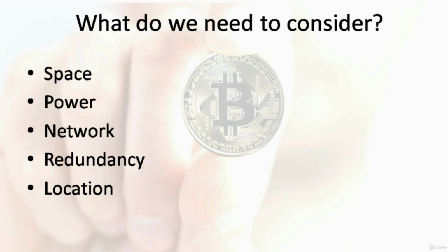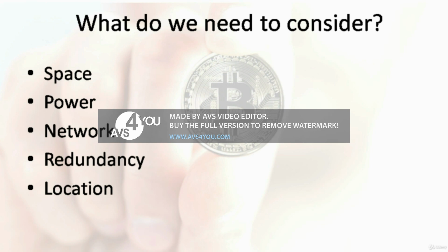The thing is that if you size it as stringently as possible, you might have cases where you have overload, or if you want to change rigs in a way that requires more power, you might overload your service, and you don't want that. So you should put a buffer on whatever you estimate for your projected power consumption.